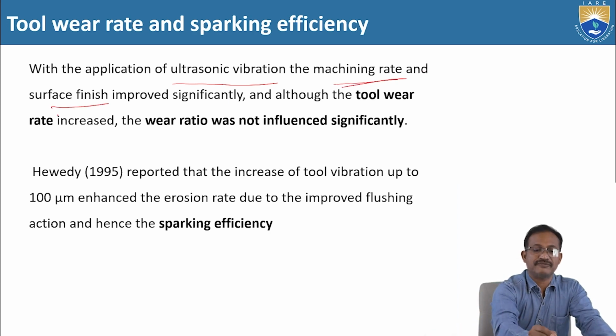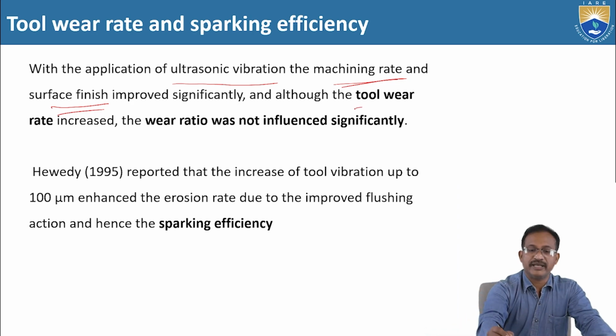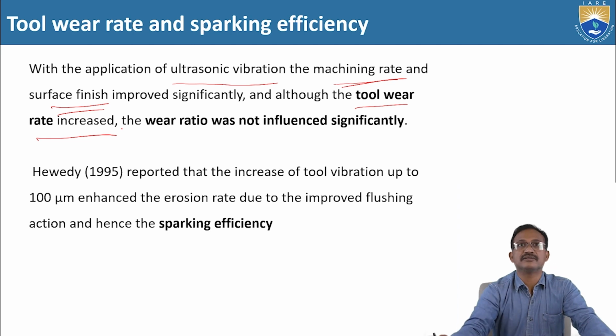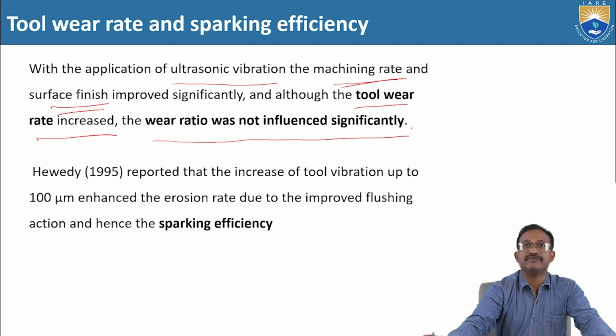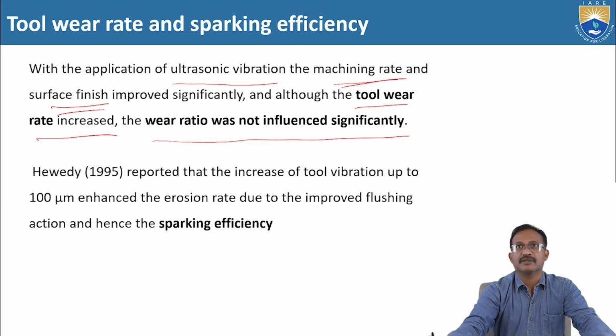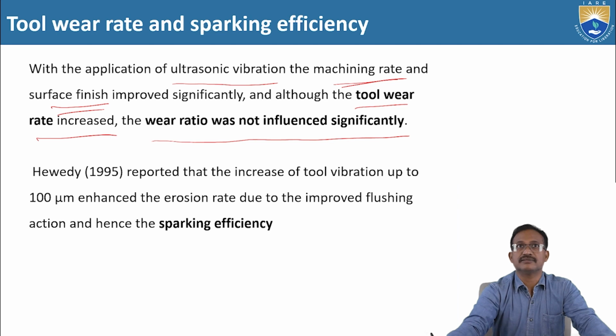Although the tool wear rate increased, the wear ratio was not influenced significantly. So here the tool wear rate has increased because of the ultrasonic vibration and the electro discharge machining.